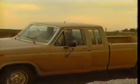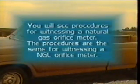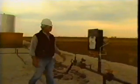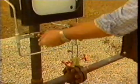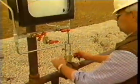Witnessing begins when all parties have arrived at the test site. At that time, always create a good working relationship with the other party. Check the area for hazardous conditions, for example, corrosion, leaks, snakes, wasps, etc. Check to see that the meter station has been operating correctly. Now take the density readings and samples before taking the flow recorder out of service. Always remember to take the meter out of service and be sure to inform the proper personnel.